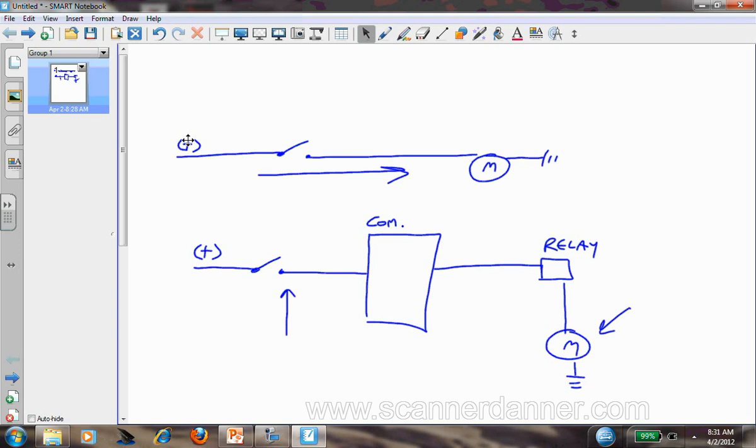The top picture that I'm showing may have 14 gauge wire going to the switch. And on older door lock assemblies, when you pulled the panel off, they had real heavy gauge wires going to the switches. But today's cars, when you look at the door lock switches, they're real small gauge, maybe 20 gauge wire. And that's because they're switch inputs. They do not carry the current at all. It's just an input to the computer for when to do it. So that would be the biggest difference between a switch that directly controls something and a switch input.